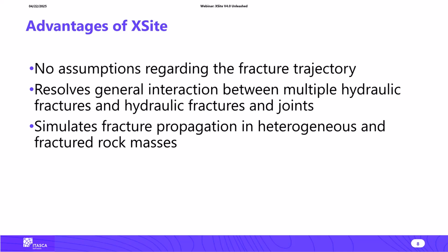It resolves general interaction between multiple hydraulic fractures, resulting in models that can show fractures deviating, attracting each other, or deflecting. Also, XSite can simulate general interaction between hydraulic fracture and pre-existing fractures or joints, where those joints can result in arrest or deflection of the hydraulic fracture.